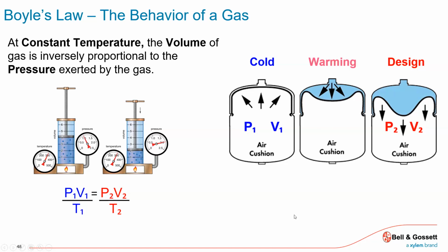And as it's doing so, what is it doing to the air pressure? Squeezing it. So it's raising the pressure. You could look down on a mechanical and look on a gauge, and as the boiler's firing and the pressure's climbing, you're just watching the air getting squeezed. That's reflecting the increase in pressure in the system. The whole key is just make sure it stays below our relief valve, and we're good to go. Everything's going to be fine.